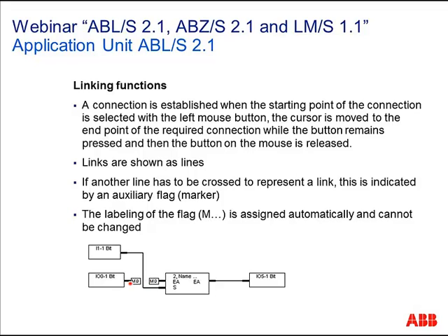Later, when you click on a marker, all other markers with the same value 0 are marked, and then you see this input is also linked to several modules, for example. To unlink, you click on the marker, or you click on a line and press the delete button on your keyboard, and then this line will be unlinked.